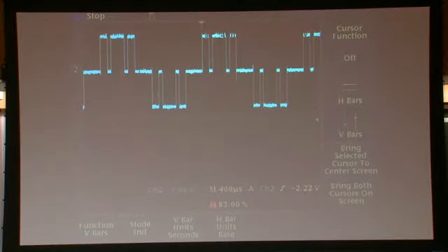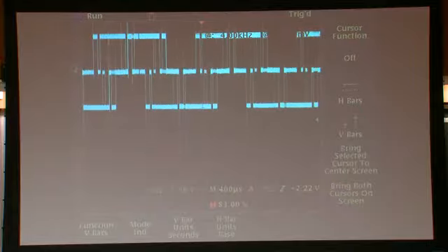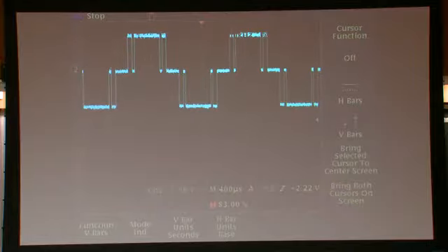Now we can take this a step further. Let me run it and stop it. Okay, now if we move back, the second spike occurs at 5.3 kilohertz, which is the ninth harmonic. So we eliminated all the lower third, fifth, and seventh harmonics.